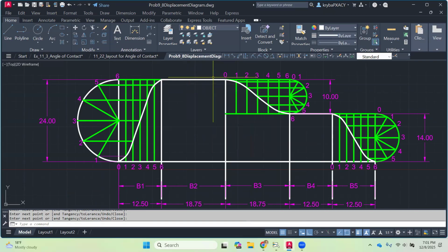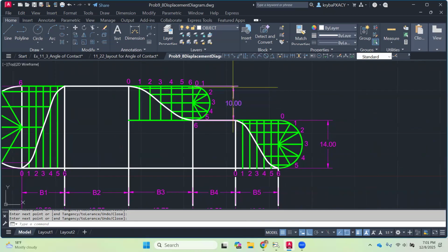Okay. Now, the next section here for the next 90 degrees, beta 2, this is a dwell. So all that's going to do is it's going to stay at that top point on my rise, and I'm just going to stay there for 90 degrees. Okay, my beta 2. Then I'm going to fall 10 millimeters, right?